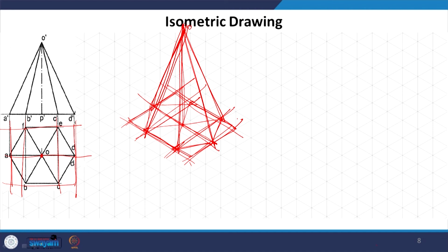So, if you look at the reference figure also, and you see that there are certain parallel lines or lines which are parallel to the axis, they must appear so in the final isometric projection as well. There should not be any deviation from that, where a parallel line now does not appear parallel. In case that is so, you automatically know that there is some problem.